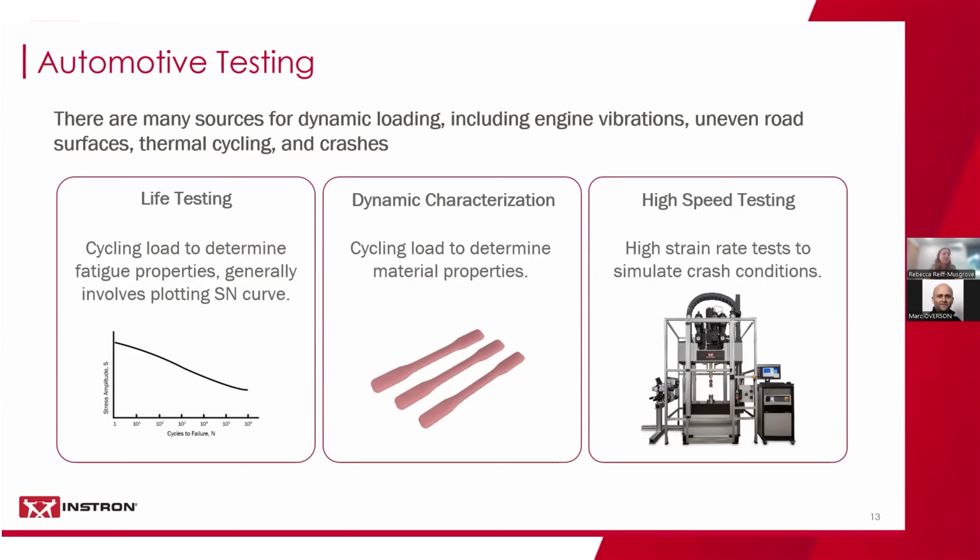Something we typically see in automotive with live testing is people doing a lot of testing to build up something known as a materials database. So how their material responds over a whole range of stresses, over a range of perhaps different temperatures, humidities or heat treatments, so that design engineers can take that database, look at their car and work out which material to use.